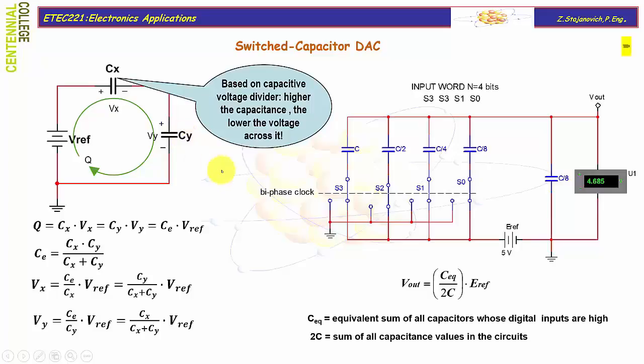Let us now review the properties of a capacitive voltage divider covered in a basic electricity course. In the shown series circuit, upon completion of the transition process, there will be equal electrical charge on each capacitor. So charge is common for a series circuit. Recall that the correlation between capacitor charge Q and voltage across it is given by the formula Q equals capacitance times voltage.